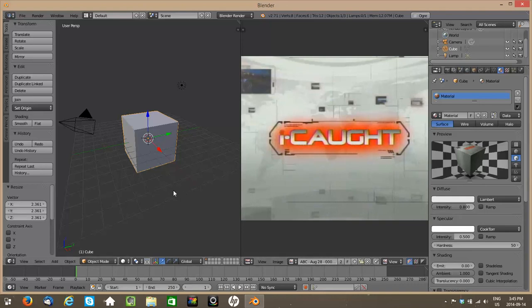One important concept to remember in Blender is that in order to do UV mapping, we must switch our editor from object mode into edit mode. And the reason for that is because UV mapping takes place on a vertex for vertex basis. So then it makes sense that we would find the tools in edit mode and not in object mode.